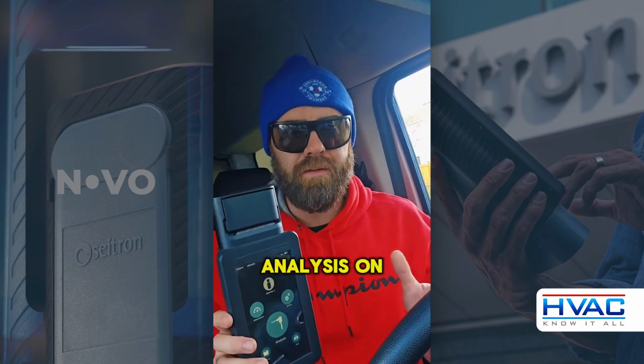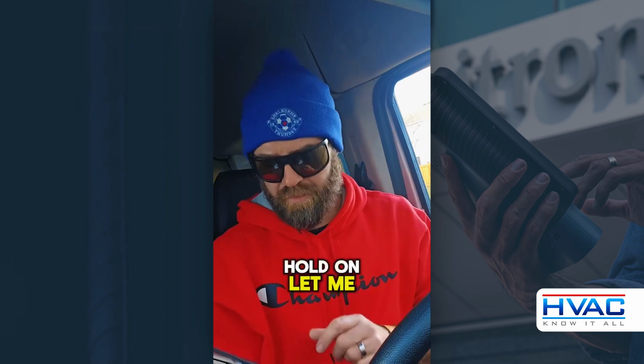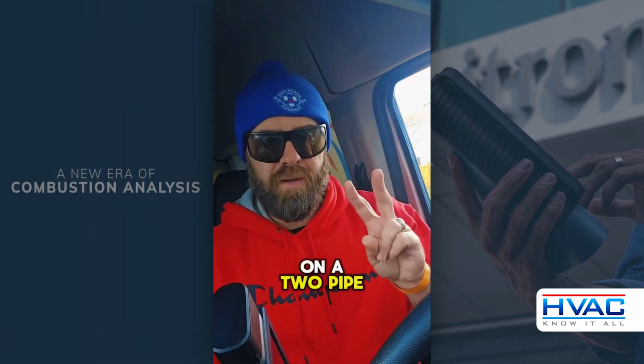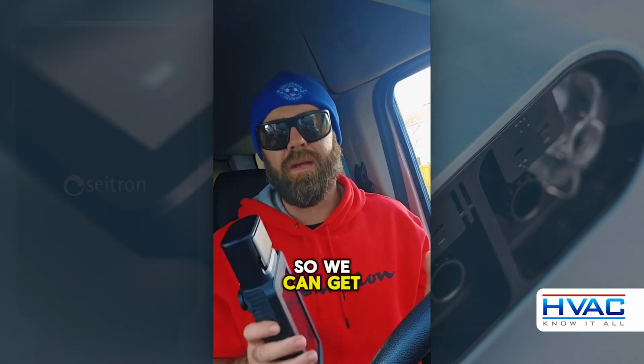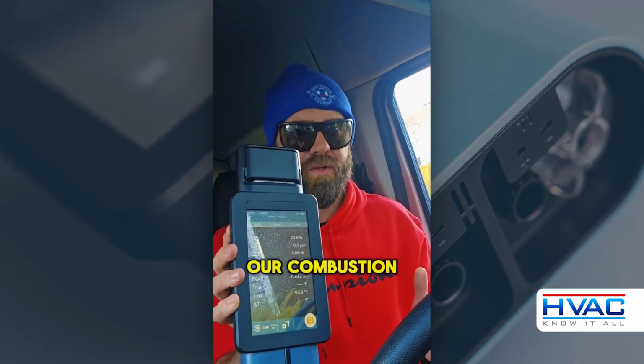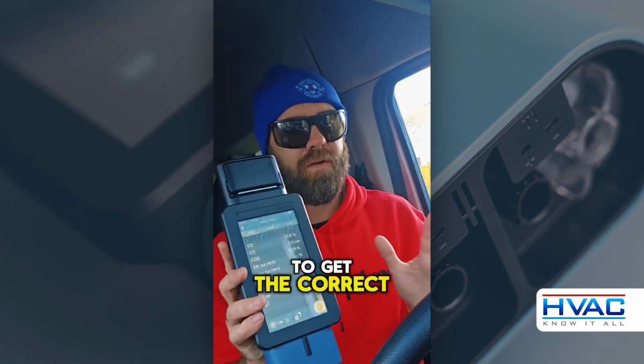When performing combustion analysis on a two-pipe system, there are considerations we need to take into place. Hold on, let me switch the pump off here. So on a two-pipe system, the air intake could be any given temperature. We need to know what that is so we can get the correct efficiency with our combustion analyzer. This is the Seitron NOVO, and there's two ways we can do this to get the correct temperature.